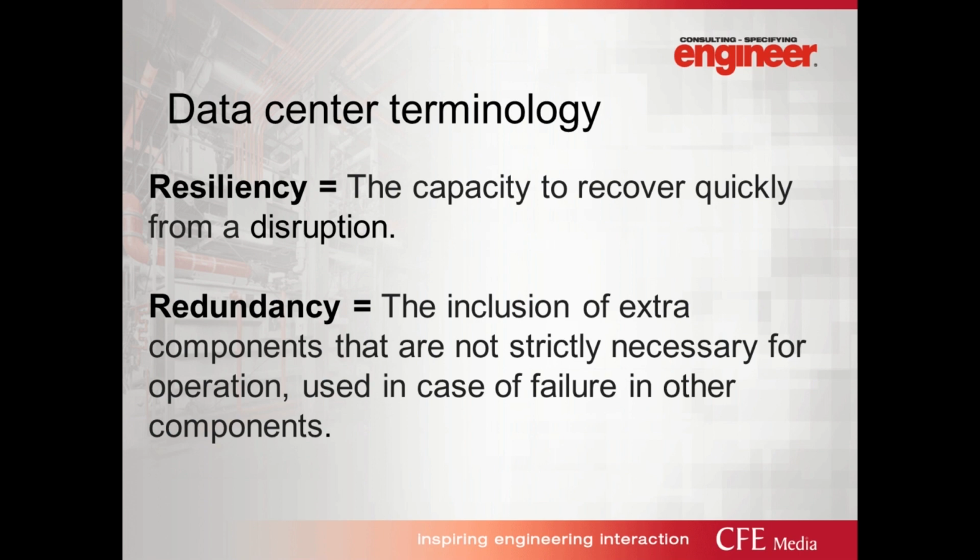So one thing that we do, in addition to writing the OPR, is going through a failure mode analysis with your power system, and looking at every single location where, if you remove this component or that distribution path, what happens? Can you tolerate that or not? And by going through that exercise, you'll be able to clearly define what it is you need to do for your owner without simply saying, I want to be tier 3. That could mean a number of things.